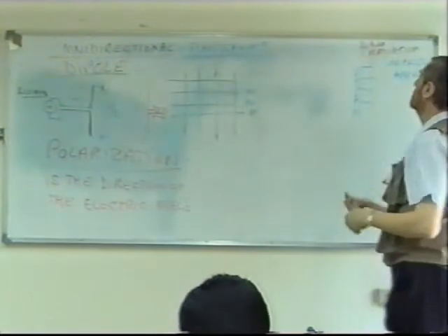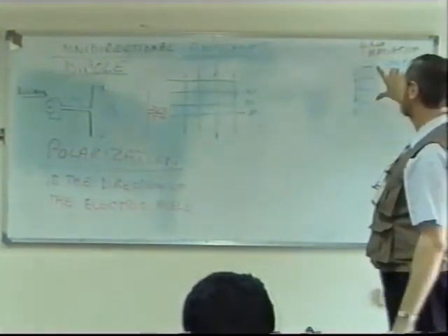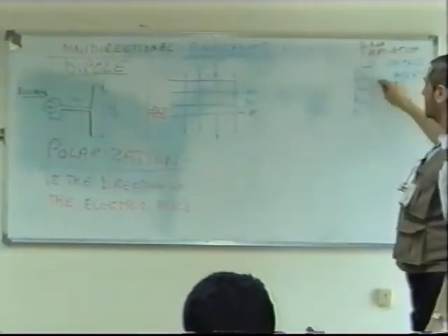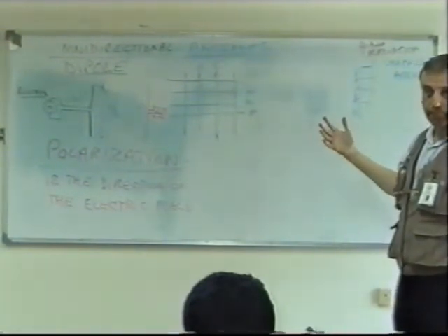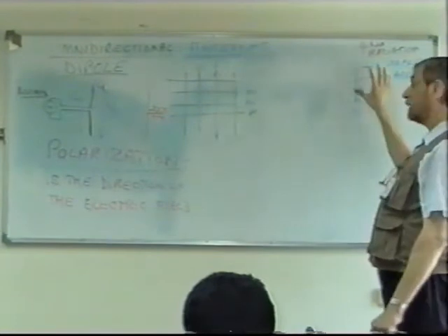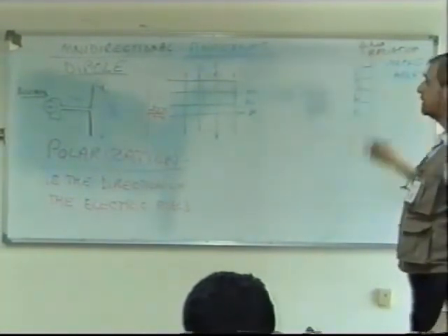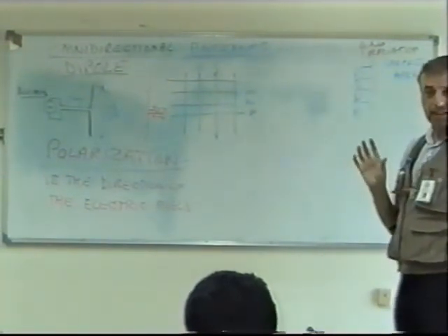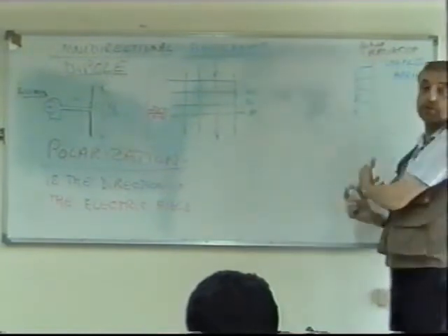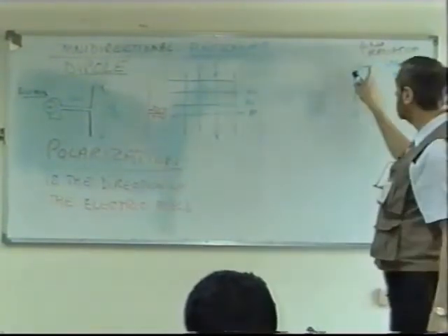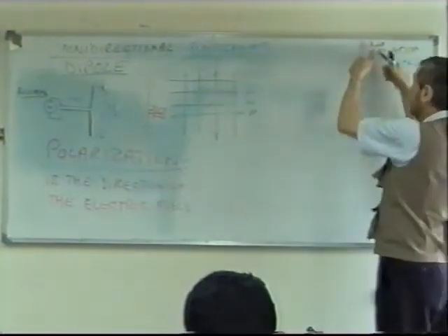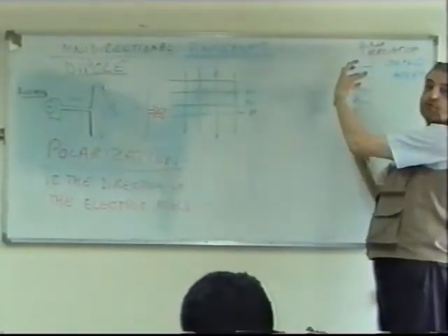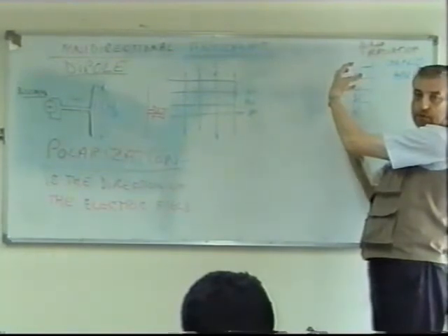Now, it's difficult for me to explain that without the mathematics, but a stacked array like this produces that radiation pattern. And it's quite complex. These stacked arrays are worked out mathematically exactly how. You cannot just get 4 dipoles and connect them together. The way they're connected to the transmitter, we treat that as one solid antenna. We don't treat it as 4 individual dipoles.